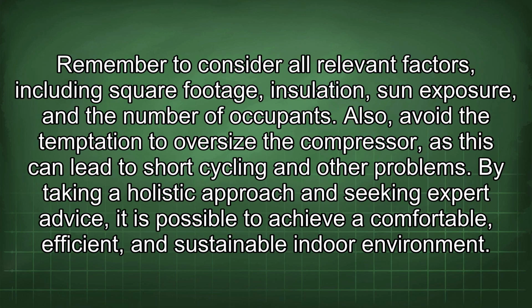Remember to consider all relevant factors, including square footage, insulation, sun exposure, and the number of occupants. Also, avoid the temptation to oversize the compressor, as this can lead to short cycling and other problems. By taking a holistic approach and seeking expert advice, it is possible to achieve a comfortable, efficient, and sustainable indoor environment.